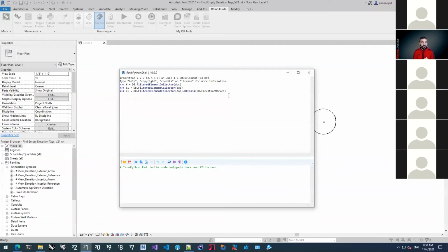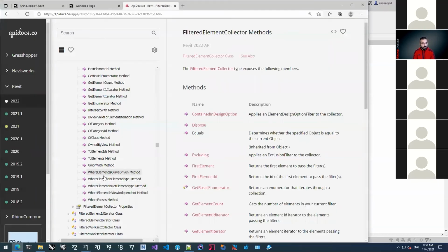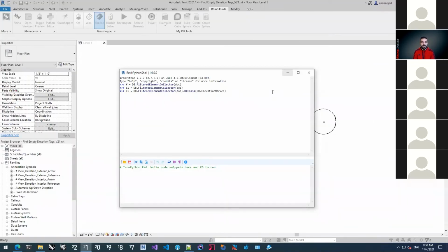So if I filter all the elements that are of category wall, then it'll give me all the wall instances in my model and all the wall types in my model, because both of them are derived from DB.Element, and that's how the Revit API works. And that's why you see these cleanup functions on it, like WhereElementIsNotElementType, for example. So I want to put that at the end.